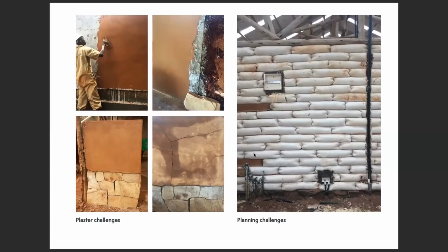And of course, the substrate is also very, very important. Lime is not something that is going to hold on, say, something like a concrete block. It will not hold there. So you need a very soft surface, which is perfect. Earth is a good surface for lime. It will bond there easily.